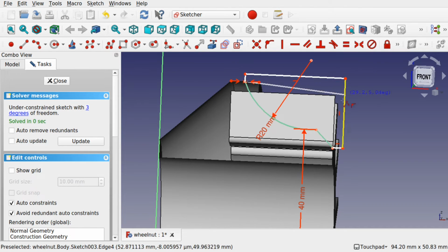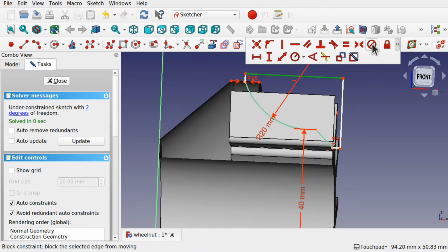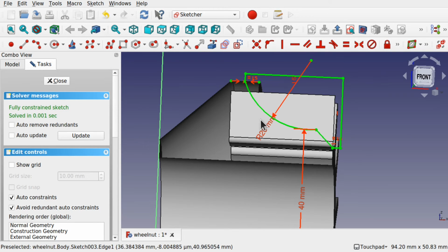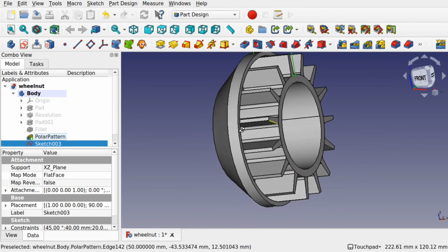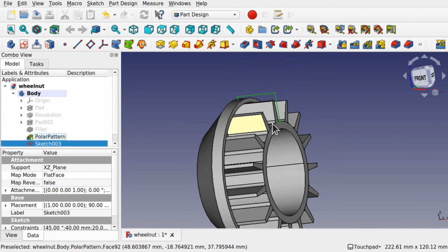So we're auto constraining all the way through there, and we've created a closed shape. Now normally what I'll do is come in and set heights and widths along here, saying these two could be equal, and set a length and a height. We can quickly do this, but what I normally do is take the lock constraint and lock that all down so it's all ready to go, just for speed. Hit close. Now we've got something to go around and profile out this.